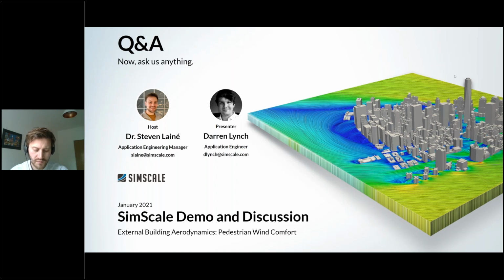Another question is, what turbulence models does SimScale support? Yeah, so the pedestrian wind comfort analysis type specifically supports what we call a hybrid model. It is a large eddy simulation model coupled with a K-Omega SST wall model. What this means practically is that we deal with the wall model much better.